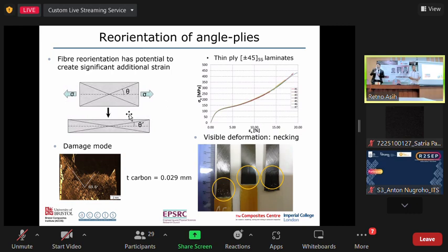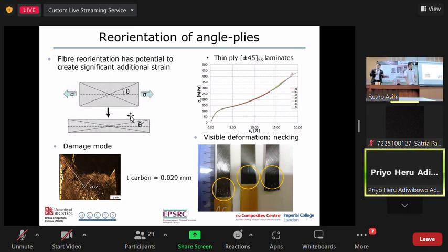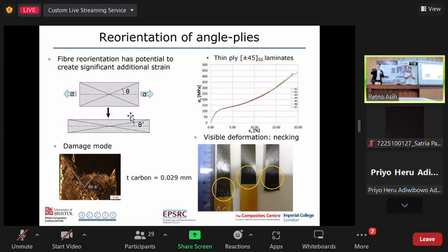Or if you're doing bending, for example, which we showed some results of, then you have shear stress as well, but it depends on which one is dominant. So it's about the competition between the failures. In some cases, like here, the competition is with the rotation, and then it fails using this type of failure. In others, it's more fiber-dominated failure. So it depends on the stress distribution and the competition between the different types of failures. Thank you for the question, these are very relevant and important questions.